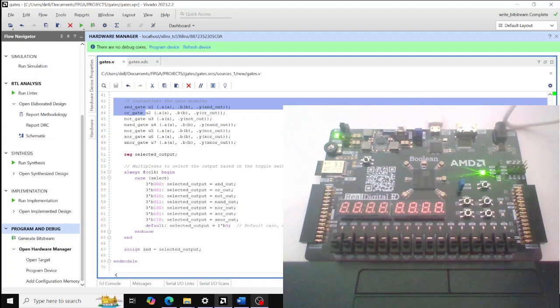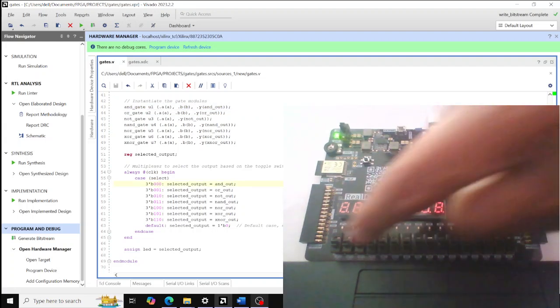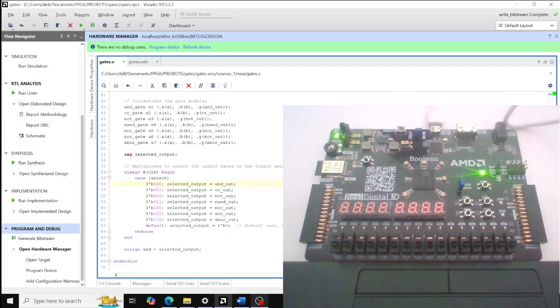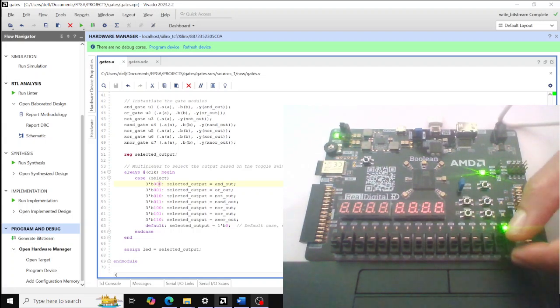Now this is our key. If I have all zeros, when these are all lowered down, these are all zeros, which means the AND gate operation will happen. If I put A high, no light will be on, because 0 1 doesn't mean on for an AND gate. For the AND gate both have to be on, so both must be 1. A single one is 1, the other is off, nothing is received. So this is AND gate operation verified.